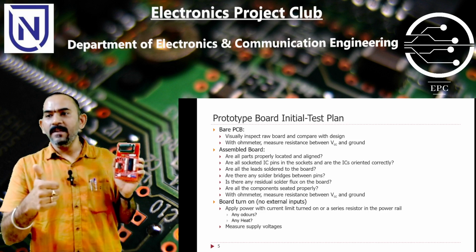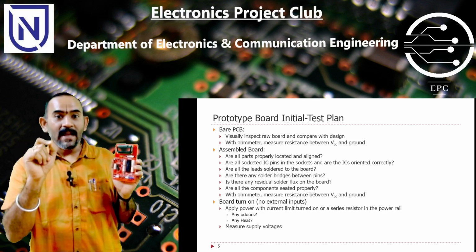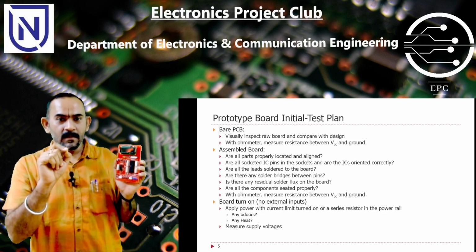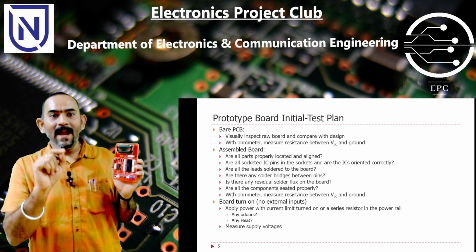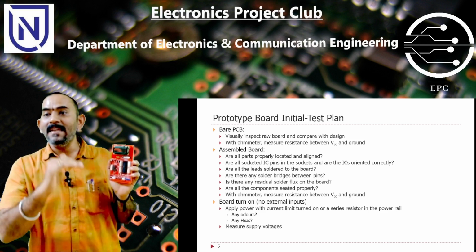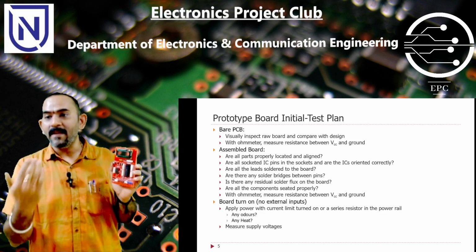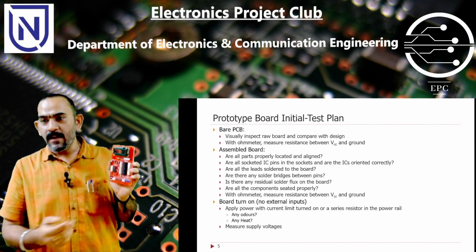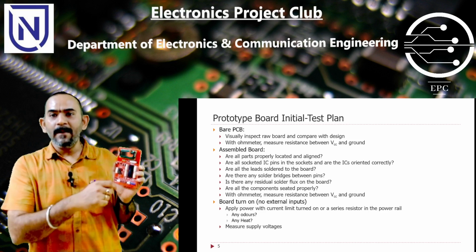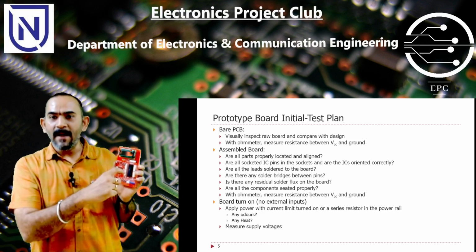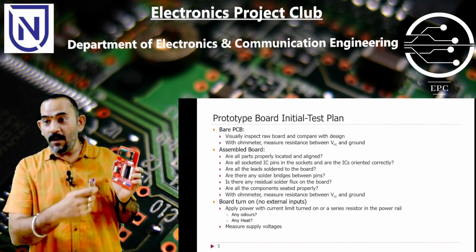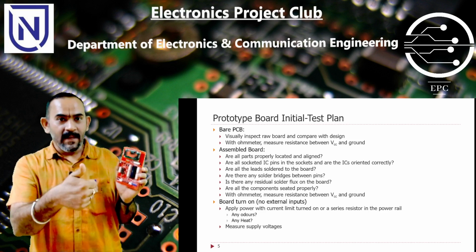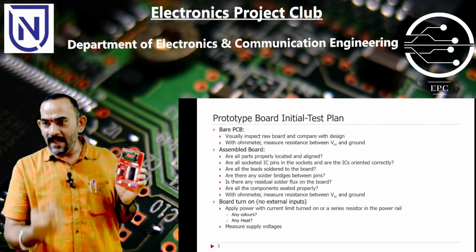The problem in doing that is, when you are soldering, you are actually heating the component, and components have a limit of how much thermal stress they can take, how many times you can reheat them. To put it in you have heated, then to remove you have to again heat.